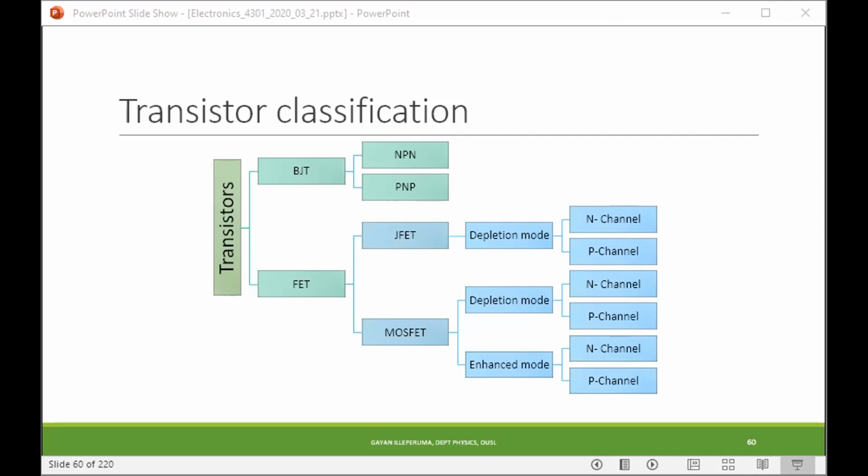Now remember, in electronics, we are talking about information and knowledge and digital signals and things like that. If you can amplify the energy of a signal, that is an active element. Amplify the energy, power, not just the current, not just the voltage, the total power. If you can amplify it, that's an active element. If you can't amplify it, that's a passive element. So is a diode an active element or not? No, that is not an active element because you can't amplify power.